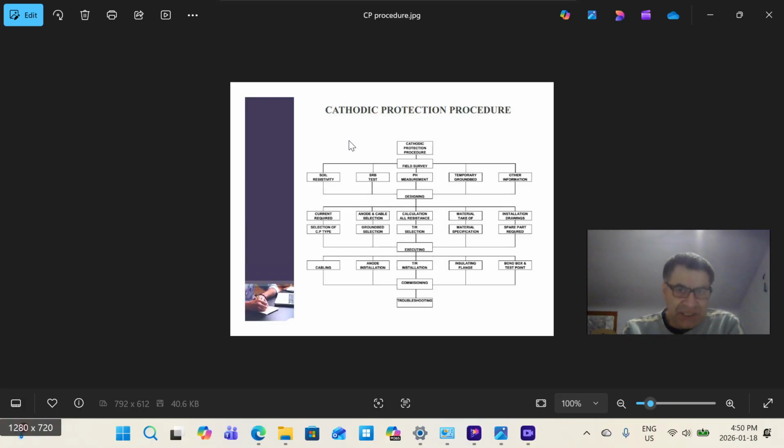The amount of moisture inside of the soil must be measured, and chemical content like gypsum, calcium or magnesium content in the soil. Another more important analysis and test is pH measurement. We need to understand whether the soil is alkaline or acidic, okay? And by doing the pH number, we can find out what type of soil we are dealing with.